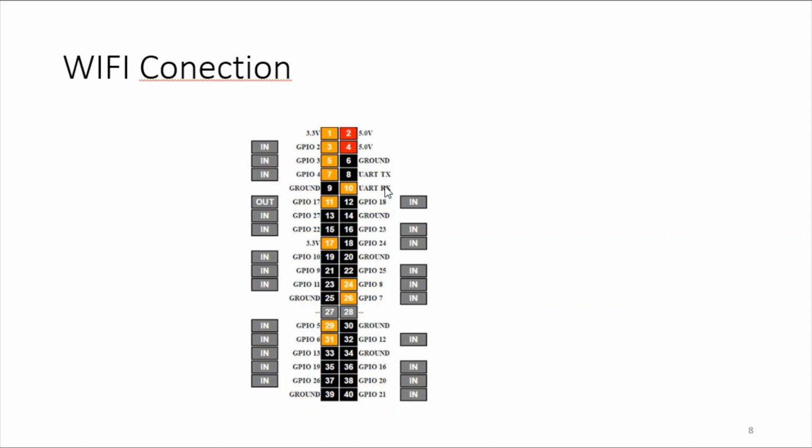For example, I use GPIO 26 here, and I also use GPIO 40. I connected them to LEDs to show that we can control the electric devices and the air conditioner. Also, I used GPIO 2, 6 and 7 for the motion sensor.